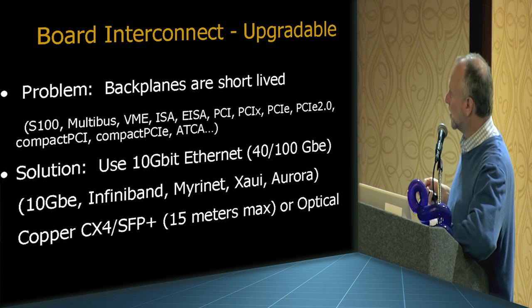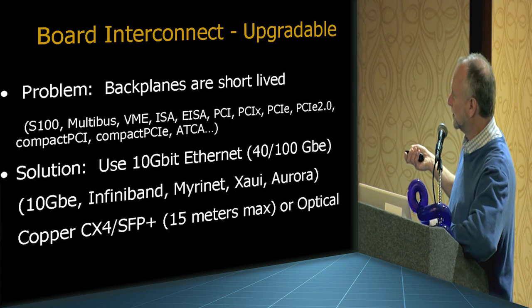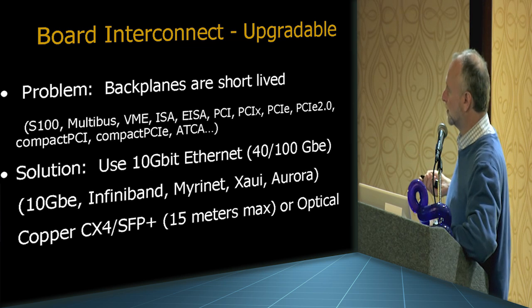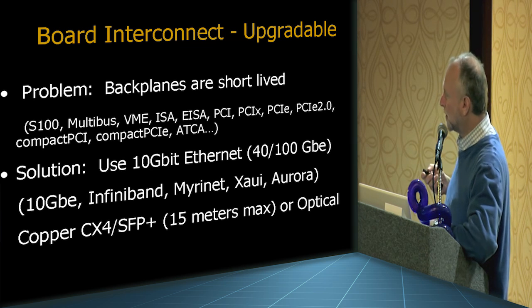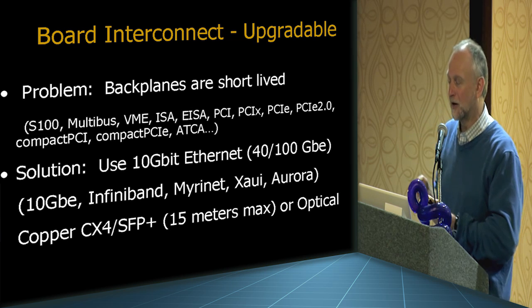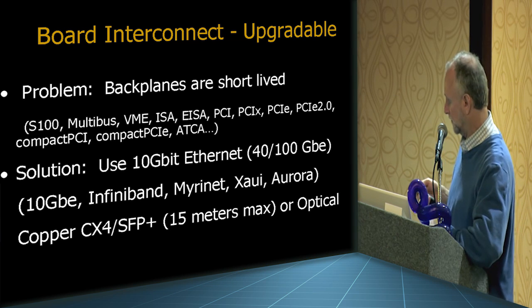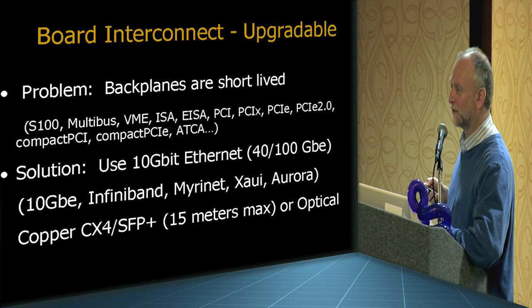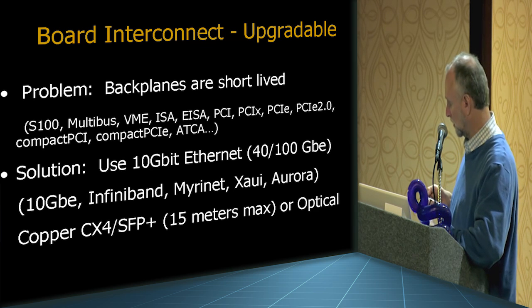Now we got stung a little bit with connectors. Our first boards had these CX4 connectors. I know everybody uses SFP+ or QSFP connectors now. So now we have these mezzanine boards that you can put on our FPGA boards that will accommodate different kinds of connectors. But I'd like to hear from you about that. Maybe we should move to RJ45 or something like that. I'm not sure what you guys recommend.